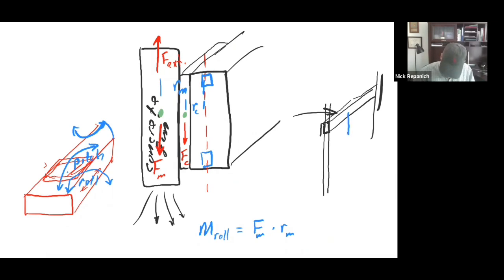There's a force on it deflecting it, so it's going to deflect a little bit. So part of what you're looking for is, do you have enough structure in the body of this that when you load it, it can handle the load? And then do the bearings actually handle the load that you're attaching to it? So you have a couple different things to think about.